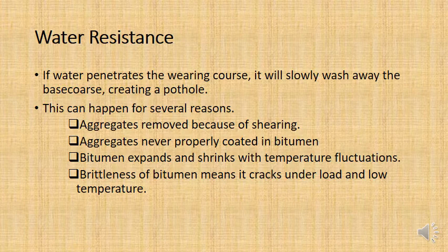Now, an aggregate can break off by shearing. So can you imagine a car driving on the road and then braking suddenly? There's going to be a shear force between the tires of the car and the surface of the road, and that friction can actually break the aggregate particles out of the wearing course.